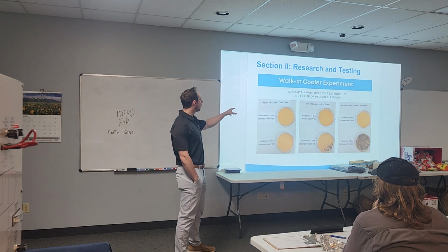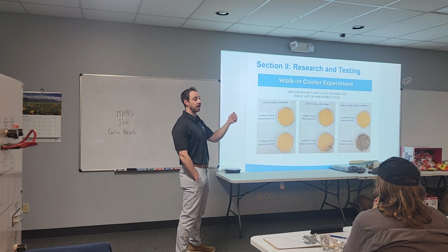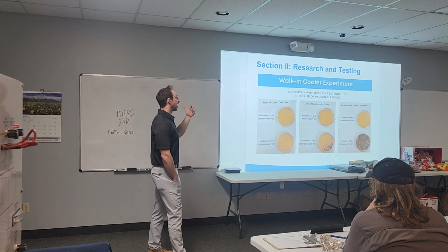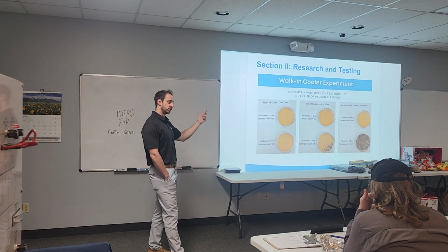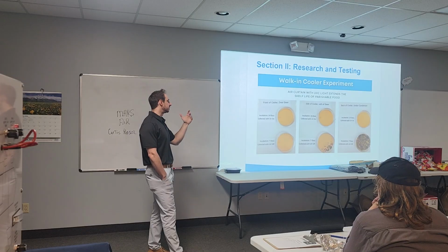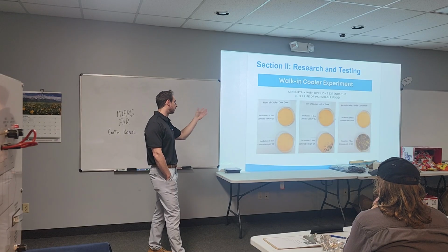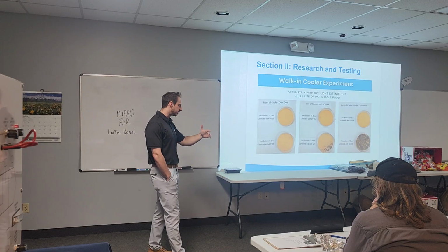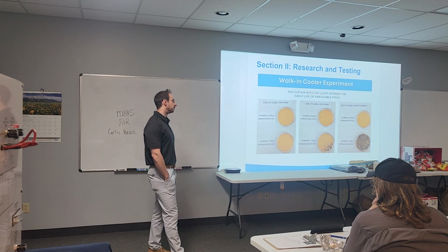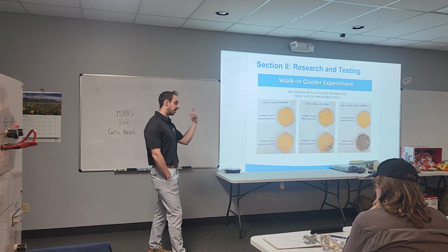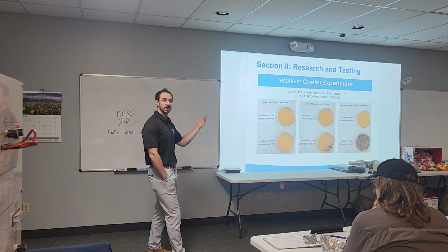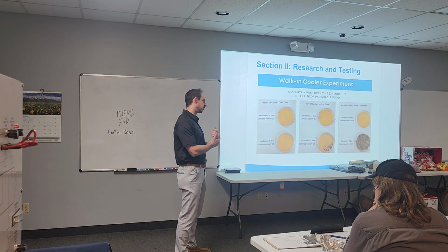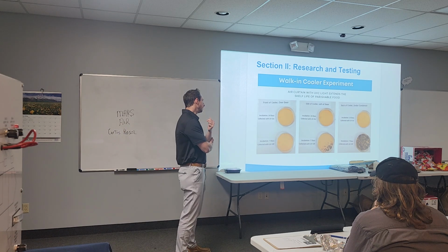So we took those out and put in a fresh set of Petri dishes. Now we turned our air curtain on with the UV function. The UV function comes with a controller and an integral timer, and you can set it. The example we did here was every 3 hours, regardless of whether the door is open or closed, the UV feature will turn on, the air curtain will turn on, and it'll run for 45 minutes, or however often you want to program it. That was roughly what we did here, and those were the results.